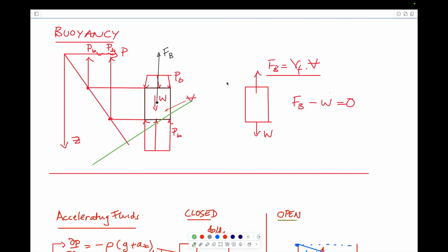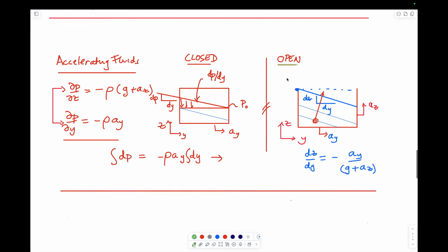There is no buoyancy question, but you know that the reason that objects have buoyancy is because if you remove this little piece of fluid, the pressures acting upwards on this structure are less than the pressures acting downwards, and so there's a net buoyant force, and that buoyant force is equal to the volume of the empty structure multiplied by the surrounding liquid in this particular case. But you don't need that.